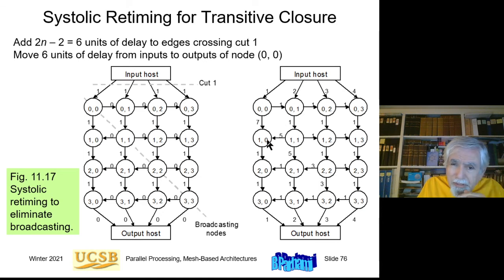So all the signals that come into a particular cell arrive at the same time, although a bit later than, or maybe a lot later than the original circuit. And using this trick, I basically removed all the 0 delays. This is a very important technique in designing VLSI circuits. So that's why I discussed it, even though the algorithm itself was not discussed.